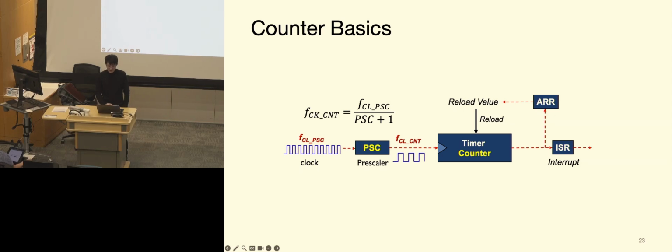So as long as it's been enabled, that's all it does, and it does it very well. Typically, whenever the counter reaches a specific number, an interrupt happens, as a periodic interrupt event. Those things happen when a certain amount of time has passed, and then it raises the timer flag and your core knows that something's happening.